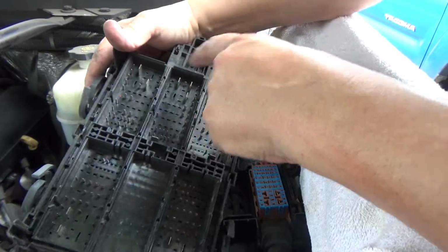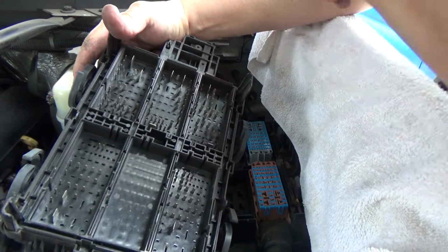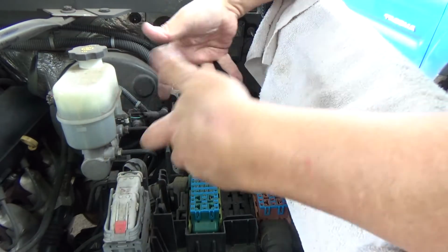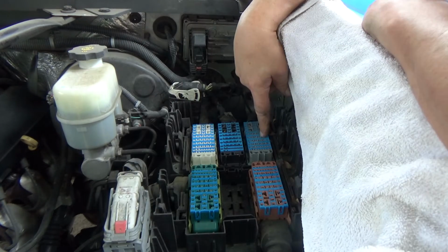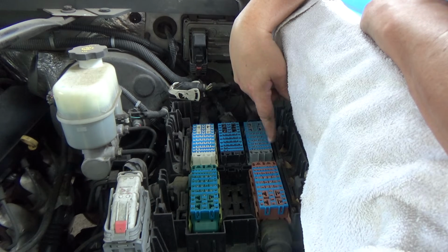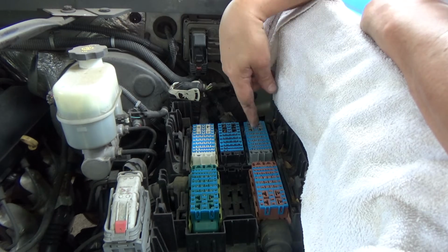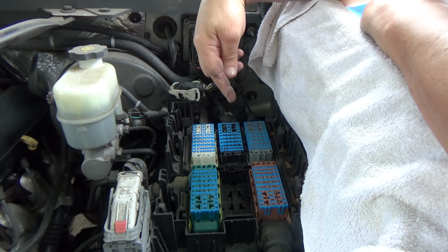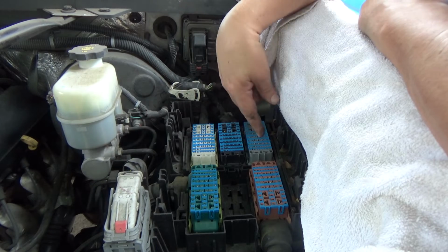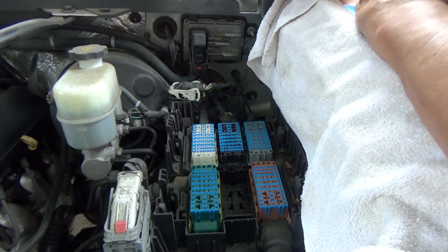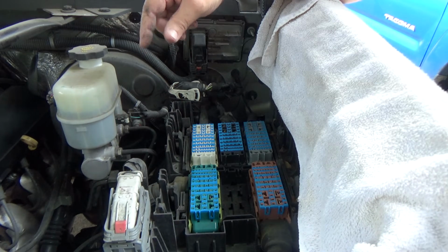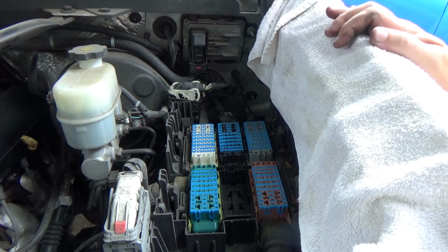How good can you guys see that? This is the X3 cavity right here, and I'll show you that on the print. I've got the print laying over there, which means that whenever that's flipped up and going down in here, that makes this right here X3. I just got to figure out which one of these terminals are running up here to the wiper motor, and then I'll jumper it, I think. I'll have to look at the diagram, see what I'm going to have to do. I'll probably have to do two, ground and high speed, maybe, to get that to kick on. Anyway, let me take a look at the diagram and figure out my next step.